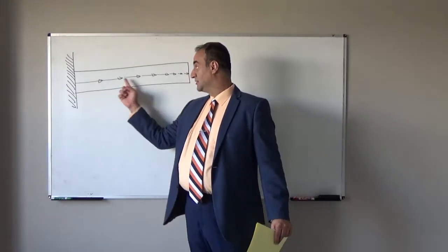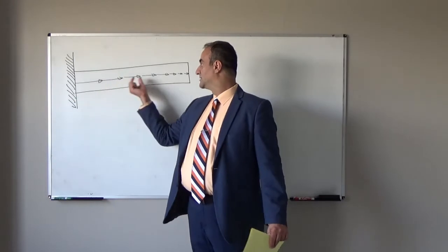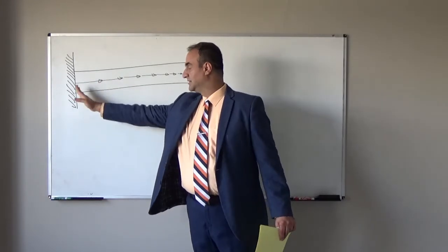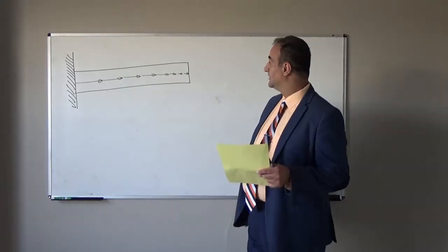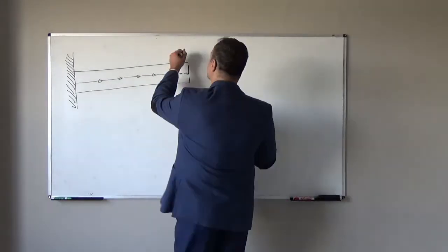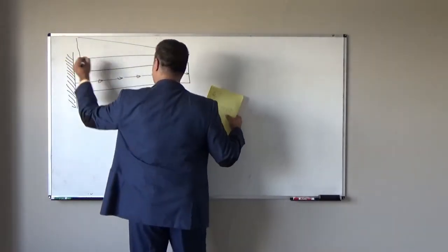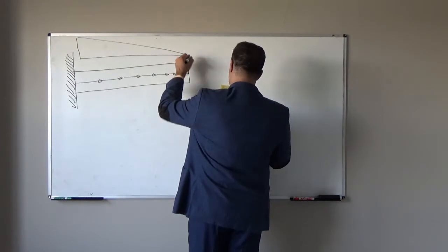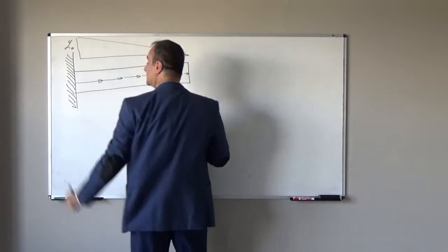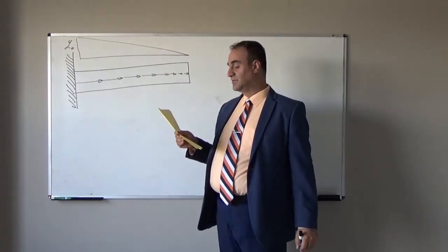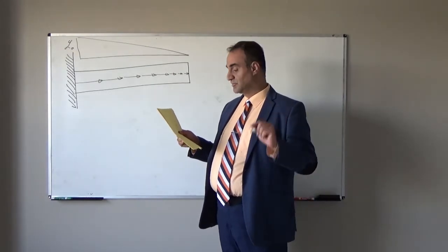It is distributed in entire length and it is non-uniform because, as you see, from fixed support to free end, it gets smaller and smaller. The variation, if I draw here, is like one triangle. At the tip it is 0, at the support it reaches the maximum value, which I show with Q naught.